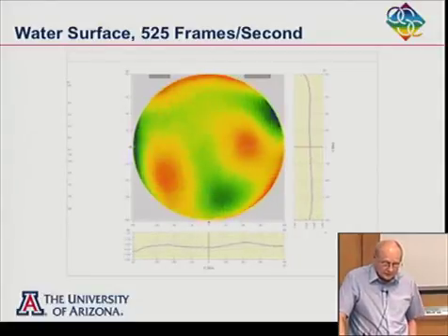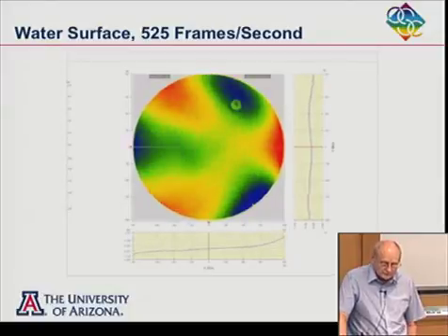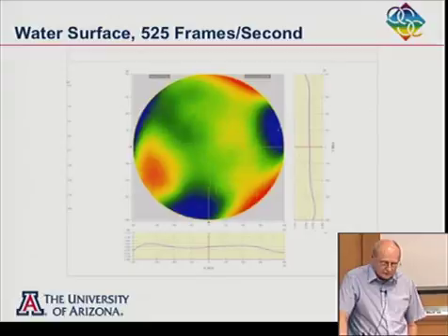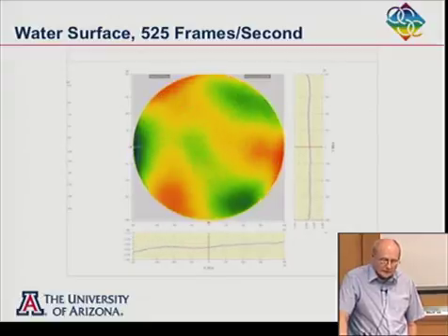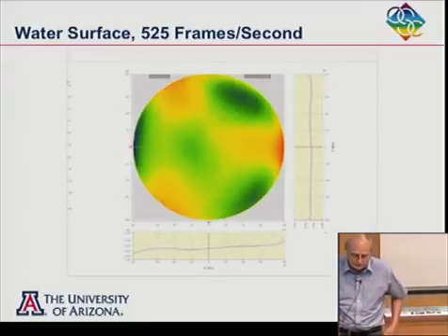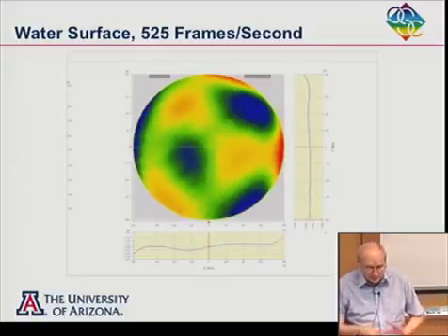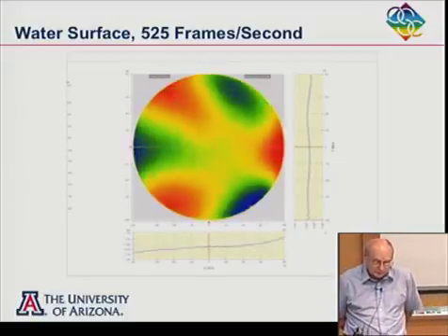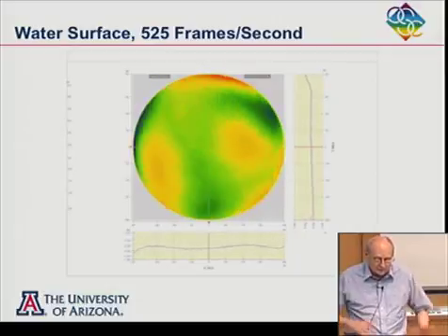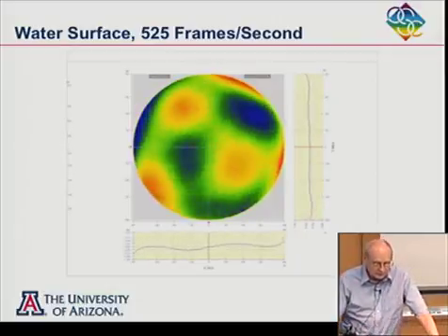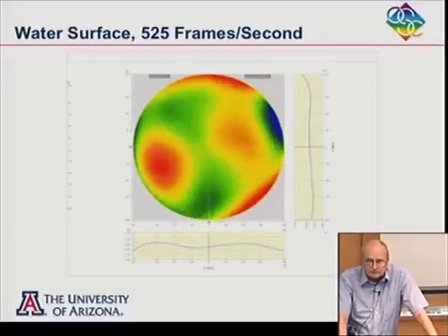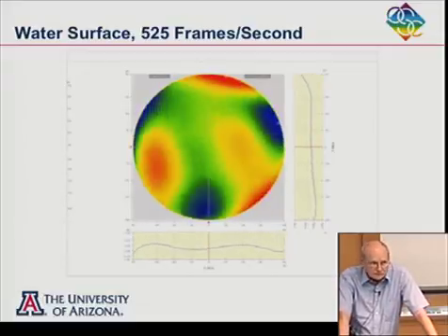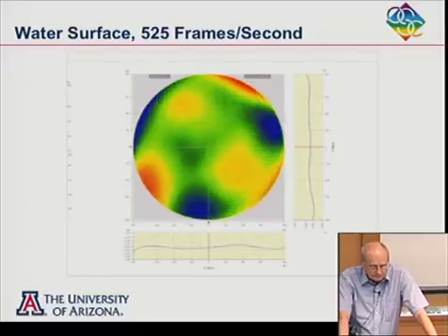And it's not a bad way for getting around the effects of vibration. Again, the thing I probably don't like about it is the large angle between the two interfering beams. The optics have to be really good, or else some way you have to calibrate out the errors in the optics that arise because you're sending the beam through at different angles. So any questions on this? Okay.